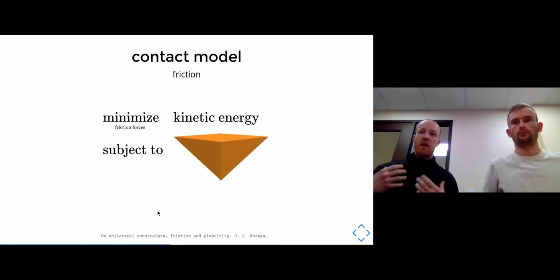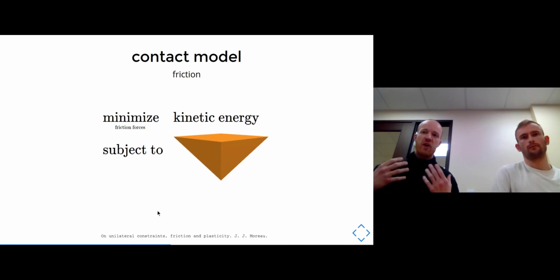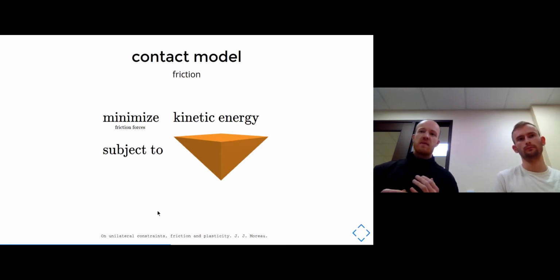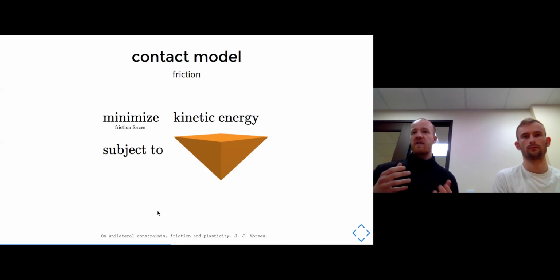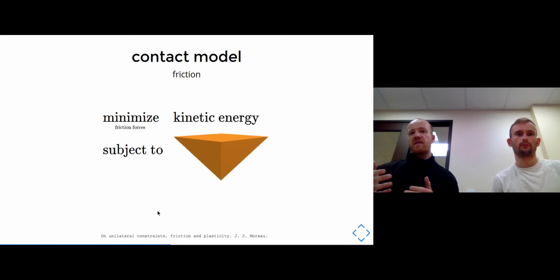Now, a really common approach is to approximate that friction cone using a pyramidal approximation. Typically this is done to formulate a linear complementarity problem, or LCP. This is used as the default friction model in MuJoCo. This is used in Drake. The reason they do this is it introduces linear constraints, which are easier to optimize. But the downside is you now have this pointy friction cone, and it biases the friction vector to the vertices of this friction cone. As a result, the friction force might not directly oppose the velocity of your system. That's how you get this kind of weird velocity drift during sliding.